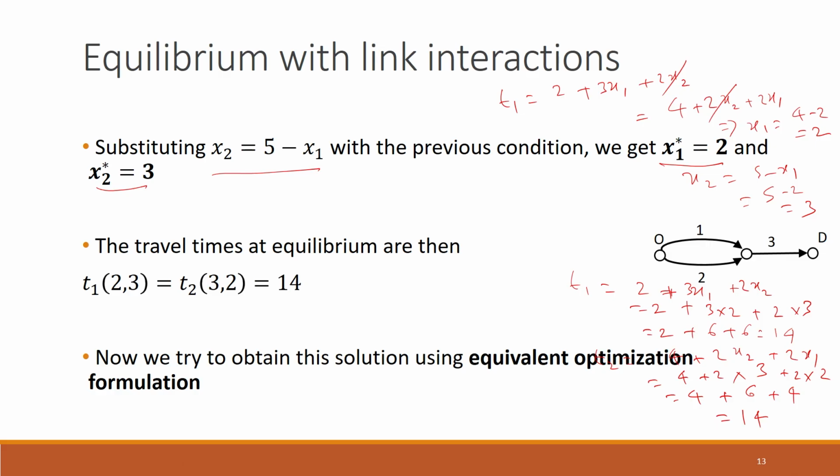Okay. So, considering these cases, let us first assume that for this OD pair, suppose this set of paths are having flow, that is they are getting used, but these set of paths are not getting used, and let us make a similar assumption for another set of paths for another OD pair and so on. So, there will be a lot of cases that you will have to consider. Okay. So, using this approach to solve the equilibrium solution is not a practical way when we have a very complex network.